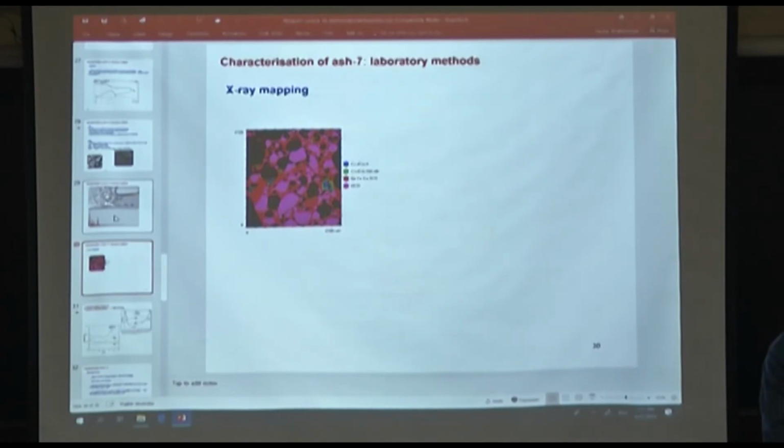So to see over the entire area of an agglomerate or a fouled section what elements are there. Again, it's a scanning electron microscopy based technique, but you need slightly different software and different hardware as well. And you can literally specify which elements you would be preferentially looking for. So it needs a little bit more specialized knowledge.